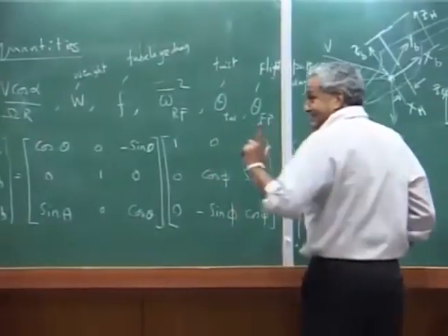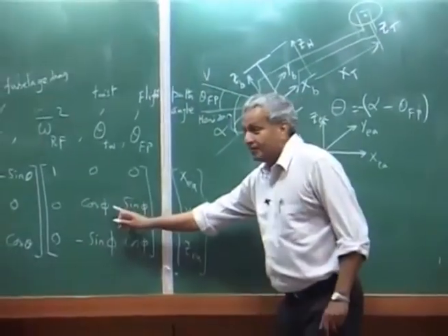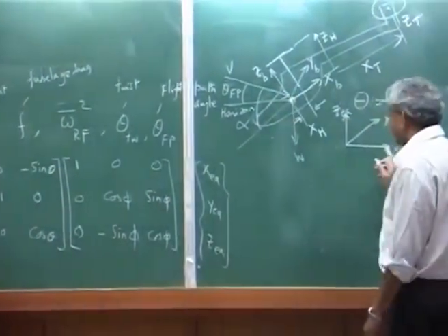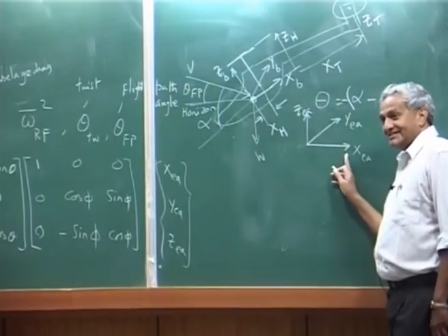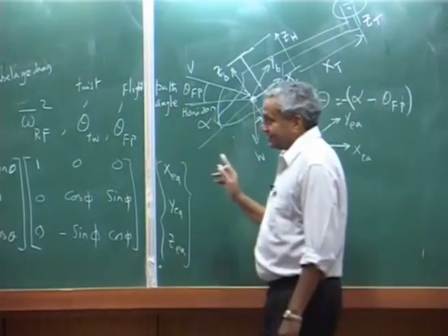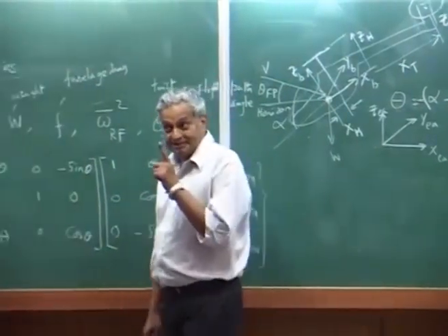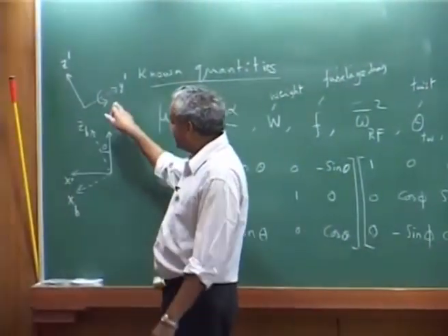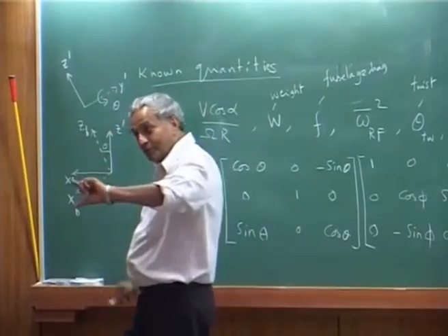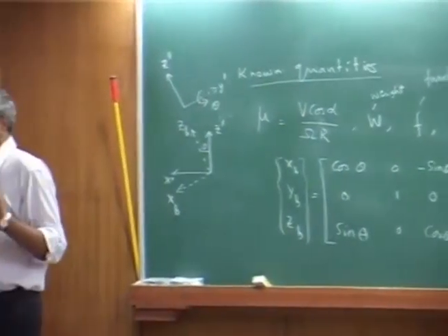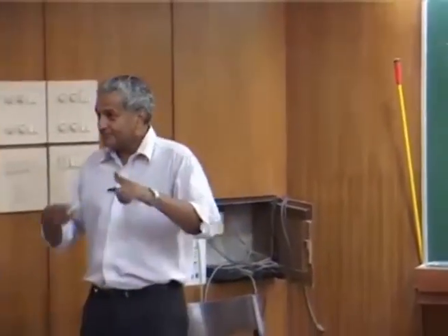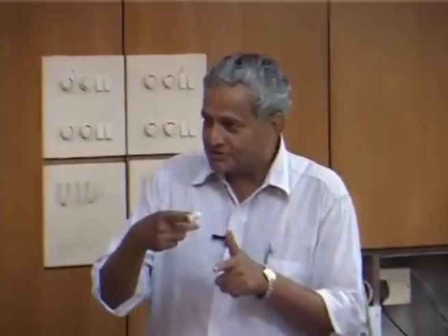Okay. Now, please understand that phi is rotated about the earth axis. Whereas theta is not rotated about the earth axis, theta is rotated about the rotated axis. Okay. It is not about the fixed axis system that you are doing the rotation. So every rotation is about the rotated axis, after you get a new position about which you rotate. Okay. This is the sequence you follow.